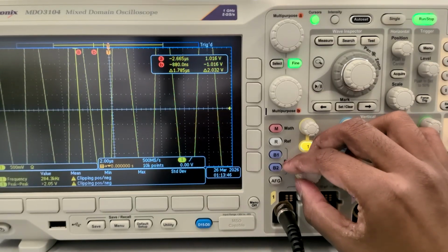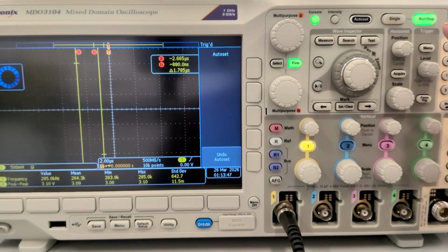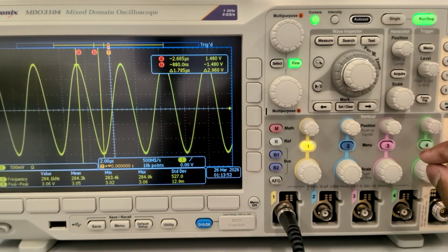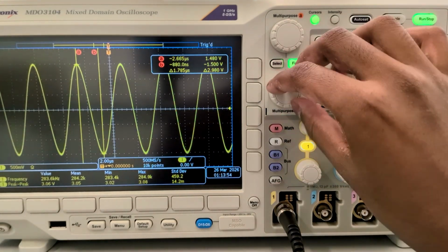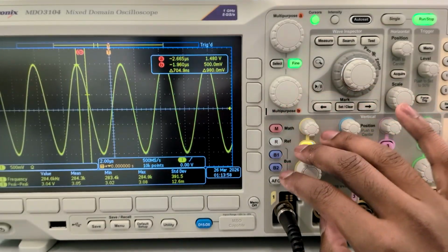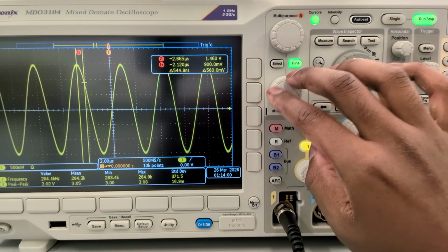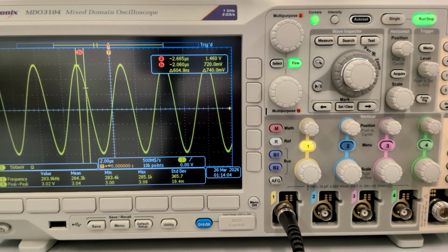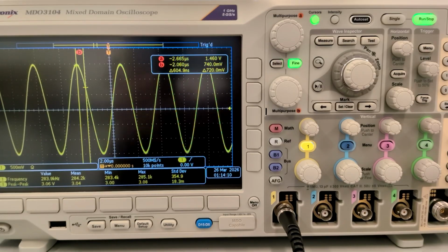And you can sort of see that delta changing as we move our cursors around. So the difference between that high point and maybe about halfway through this wave, it's around 0.76 volts, or 760 millivolts. So that feature is incredibly useful for us.